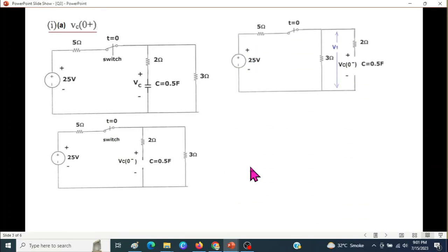How much is the voltage? It is not easy, and some students might have difficulty finding it. So what I have done, I have reversed the two positions, so the resistor is here and the capacitor arm is on the right hand side. Now you can see that whatever is the voltage here, the same voltage will be in this line and the same voltage will be across the capacitor, because no current is flowing, so no drop in this resistor. Now how much is this voltage?